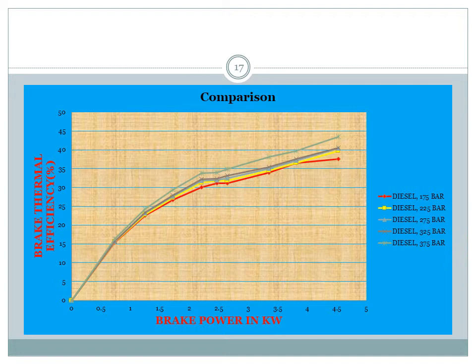This is because at lower injection pressure, combustion is not complete and more unburned fuel leaves with the exhaust gases. At lower injection pressure, the exhaust gas temperature is also high, which means more residual gas when compared with high injection pressure. At 375 bar injection pressure, more complete combustion is occurring, which means that a very small amount of fuel is required to produce the same amount of power. This is the main cause of increased efficiency of the engine at higher injection pressure. An improvement of 5.8% is seen in the brake thermal efficiency of the engine when the injection pressure is varied.